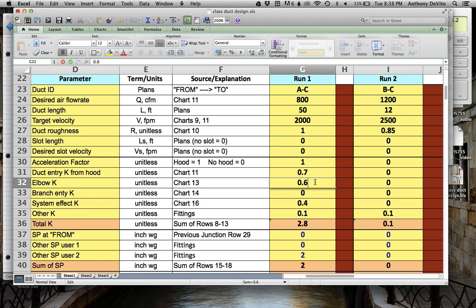Yes. That's the K value for the hood. No, the CE value is the efficiency of the hood. The K is the number that you multiply the velocity pressure by to figure out how much of a loss you're getting going through a duct or a transition or an elbow or something like that. The Ks are always a factor that's affected by the speed you're going through it. The CE is really just an efficiency factor. So we're not really going to use that for much.